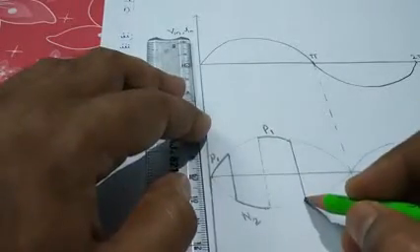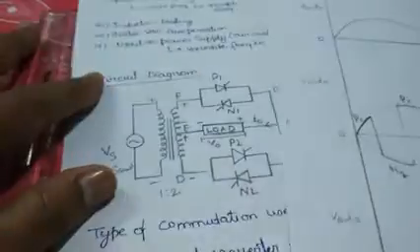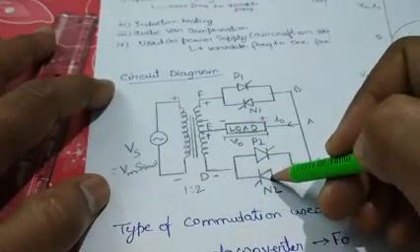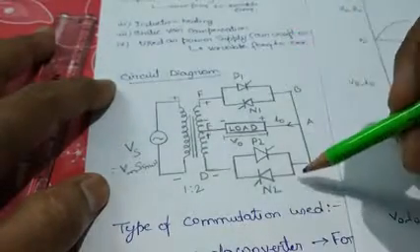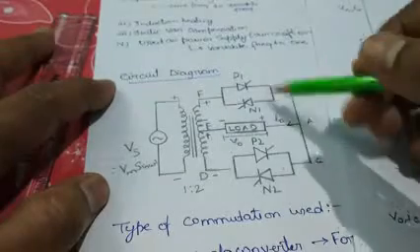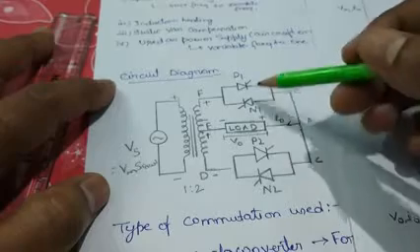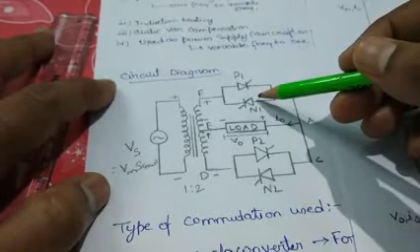We will trigger the N2 thyristor at this point the same way. Again N2 is capable of conducting. So in the interval 0 to pi, P1 and N2 are capable of triggering. They will be triggered a number of times depending upon how much we have to boost up the frequency.